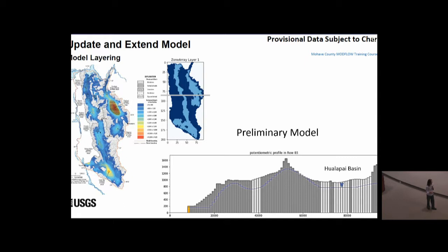And this is the simulated water table. They knew there were some springs, and they knew some water levels in the basins, and that's what they were trying to match. And of course, they prescribed the head here at the outflow at Mohave Lake. So they felt that the model did a reasonably good job of simulating the historic conditions. If they were to have more layers